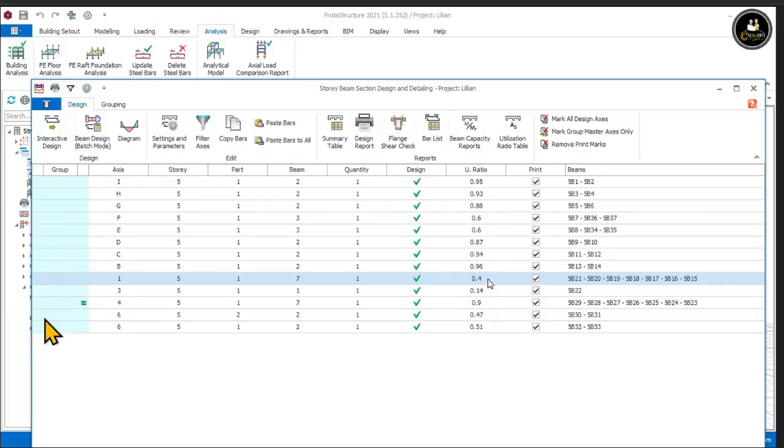40. That's a continuous beam. When we are casting, maybe you can simply add reinforcement. We really don't want to have variation of beams. Maybe in one beam span you have a depth of 400, another one you have a depth of 500. When it comes to casting, it will be challenging.